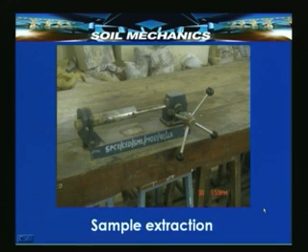Now, in the case of a triaxial test, we need perfectly cylindrical specimens whose ends are quite planar, whose sides are perfectly vertical, because it has been found through experience that a specimen which does not have these characteristics sometimes gives errors in the final results.